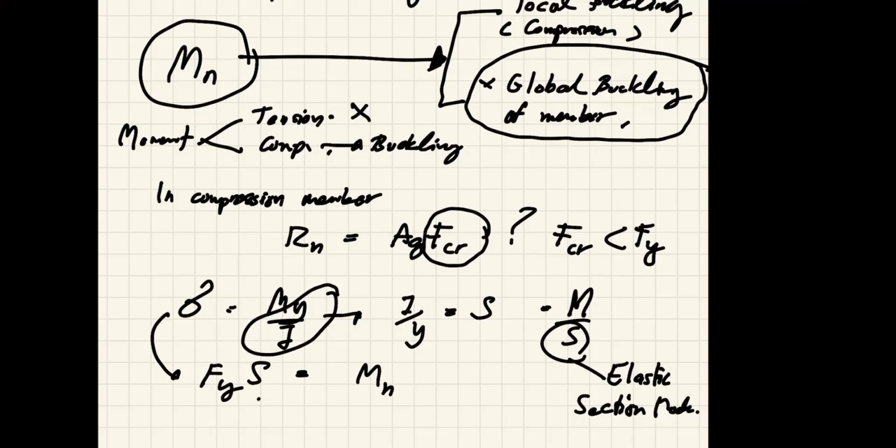After World War II, many engineers discovered that steel structures last longer than that. So this is the first yield, when the yield occurs for the first time in your beam. But after the first yield, we still have load carrying capacity left. That's why they studied further, and the behavior of your flexural member is completely different from a compression member, where you just approximate the stress where buckling occurs.